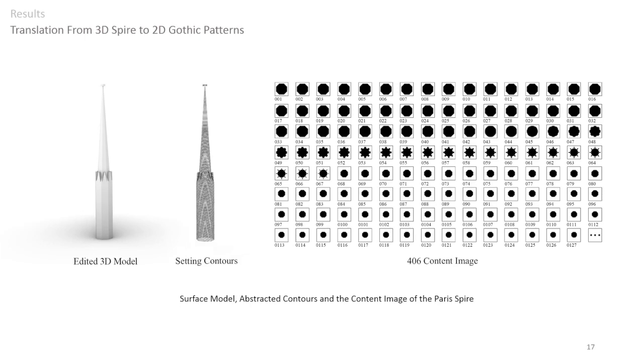The cutting level and the plan number need to be based on each building's length, width, and height ratio. Thus, according to the actual measurement of the spire and the scale collection in the Rhino model, the spire is divided along the z-axis direction with a distance of 1 unit. As a result, 406 clone contours are generated. Then, by defining the spire interior as the content and the interior area as a black box, 406 content images are exported in the top viewport with a resolution of 50 × 50 pixels.